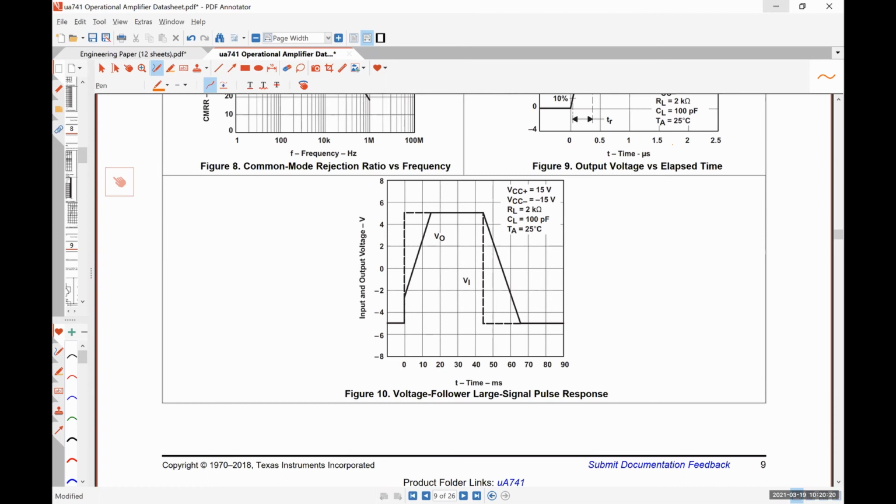The time it takes for that to happen looks to be on the order of about 13 microseconds. This is mislabeled as milliseconds. So our change in voltage is 8 volts, and our change in time is around 13 microseconds. So somebody do the math and tell me what that's supposed to be. What's 8 over 13?